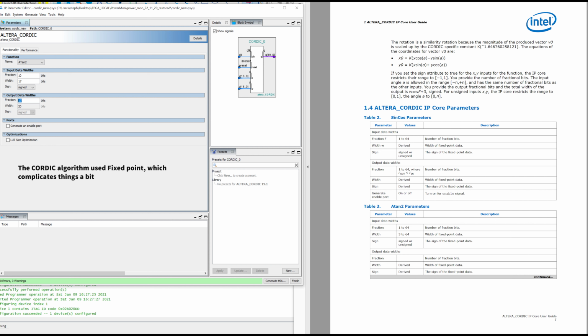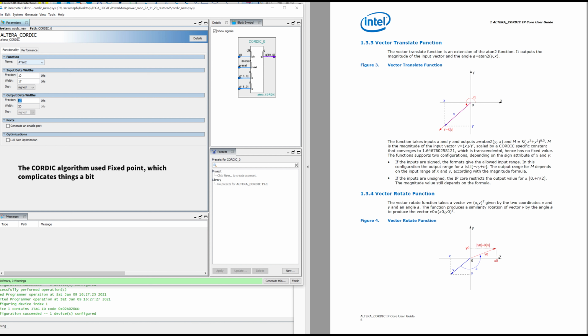Now it's a bit complicated when this signal comes out of the CORDIC. It's not in 2's complement anymore. It's a little bit complicated how you convert that back to an angle in decimal in the graphical user interface. Now, I think this is outside the scope of this video, but this is something I will address in the future. But all we need to know now is this CORDIC algorithm is performing the arctan2 function. So it's good for all 4 quadrants.